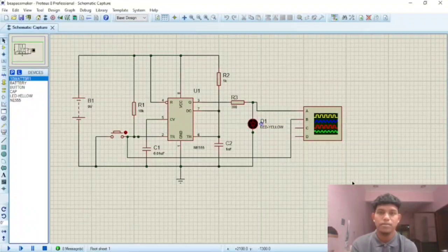So in our circuit, we are using the IC555 timer as its timing pulse. The IC can be configured into two modes, astable and monostable, and we will simulate the monostable mode. In monostable mode, the 555 timer outputs a high pulse. A monostable has a single stable state, an off state, which means whenever it is triggered by an input pulse, it switches before going back into its stable state.